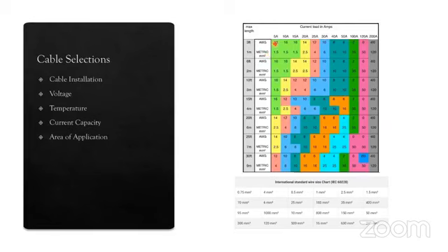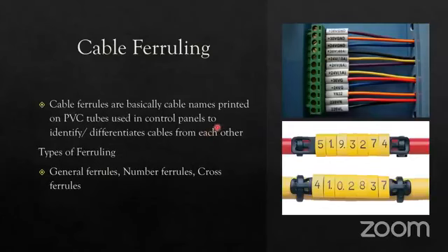So you can see here, if you require a 5 ampere current carrying capacity, then you can go for the 1.5 mm² cable up to 1 meter. If you have 2 meters, then also 1.5 will do. So likewise, the length will also affect this current carrying capacity. And these are the standard wire sizes available nowadays in the market: 0.75, 1, 1.5, 2.5. So these are the standard cable sizes available in the market. So that was for the cable selection.